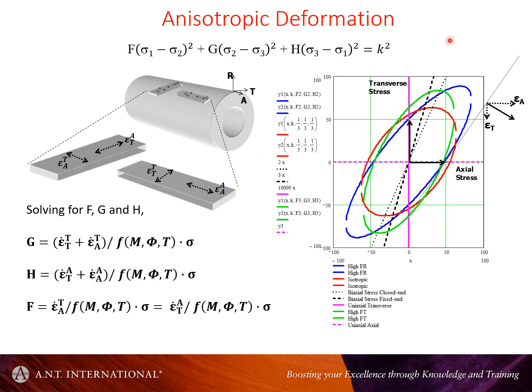But for most reactor components, when they're made, they have a particular texture and a particular grain structure and microstructure. So the anisotropic response to a given stress state is often very difficult to measure. You can't simply make tensile specimens, or I guess you can make microtensile specimens out of the component, but if you have a complicated component, that's very difficult.